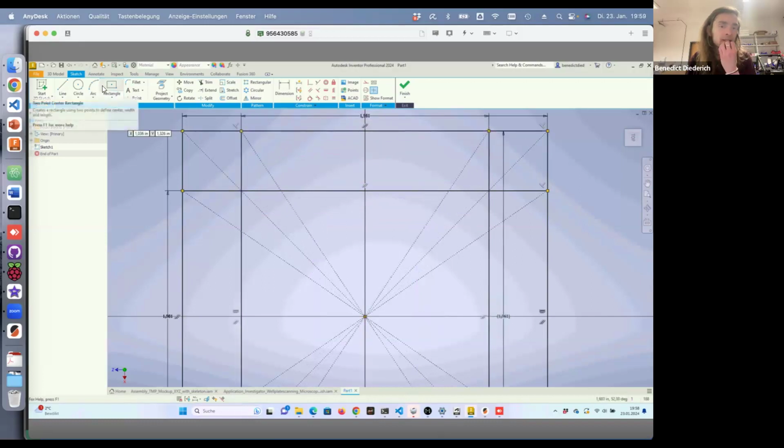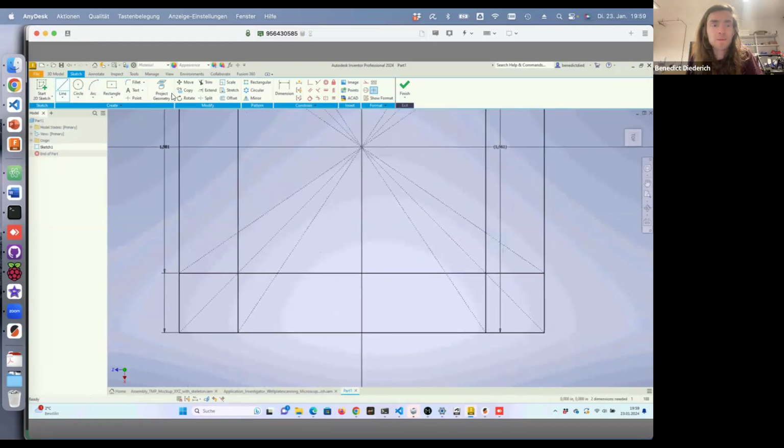So we can then extrude the stuff here. But we also have these bars here. So make sure that this has 45 degrees, and then make sure that they close. Same here on these edges. And then we have to make sure that they have the right distance from the center, essentially. I can show it to you. And then we are almost done. We essentially just need to extrude the two-dimensional drawing. So this is it.